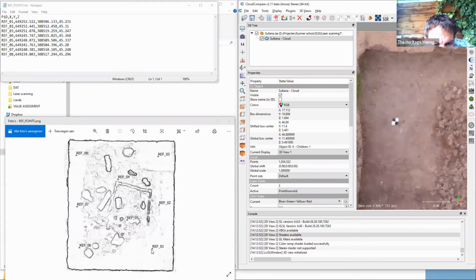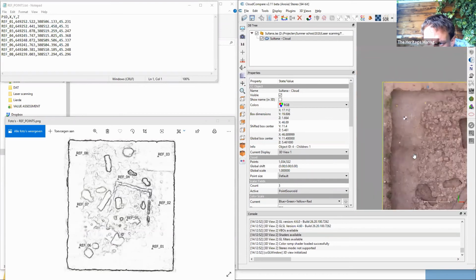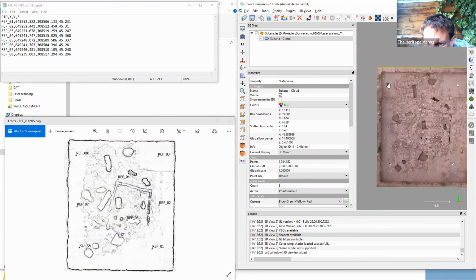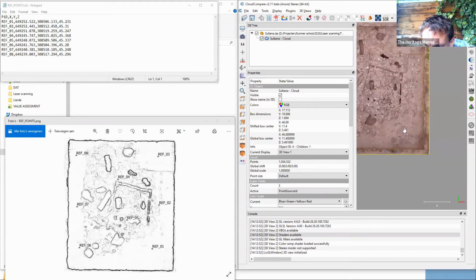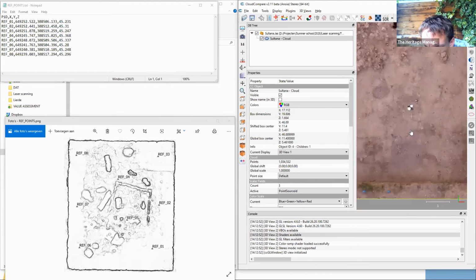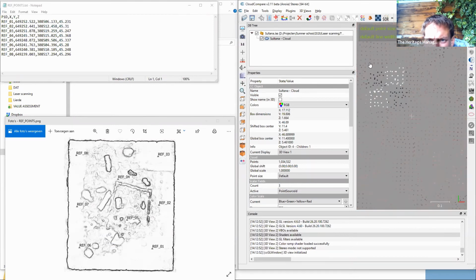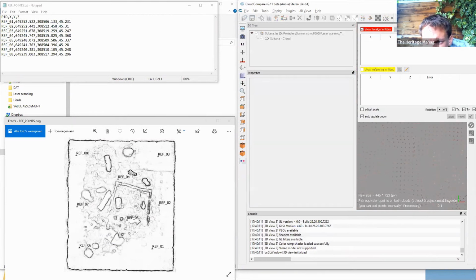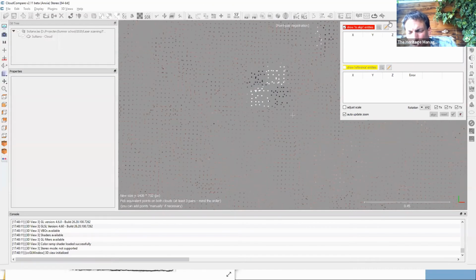I will first select my first points. Right now, you see that I'm here at point 8. This is point 7, point 6. So then this should be point 1. I will zoom to point 1, and I will open my alignment tool. What you see here are the two aligned entities. This is my slave, these are my slave coordinates, and this will be my master coordinates, my reference coordinates, my true world coordinates.